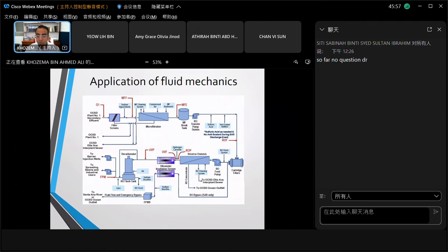So in order for you to do your job as a safety officer, indirectly, you must know the overall process flow. What are the equipments? How is the fluid being transported? Is there any problem with the mixing? You need to understand how the mixing is happening. If you see here there is a pump station, is there an error with the pump?